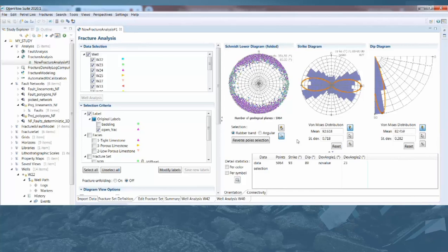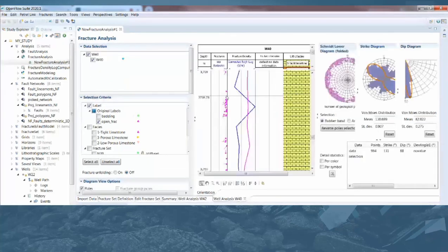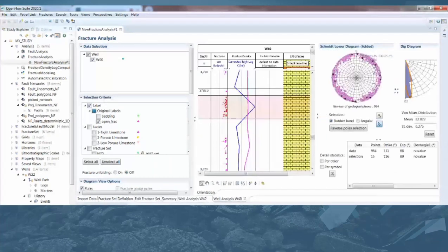So let's zoom in at this peak and select the fractures. You see that on the stereodiagram, the poles, which are the orientation of fractures, actually have a lot of dispersion. You have all orientations. So this does not correspond to the definition of a cluster. I remind you that a cluster is composed of parallel fractures in a narrow interval. So it is not a cluster.